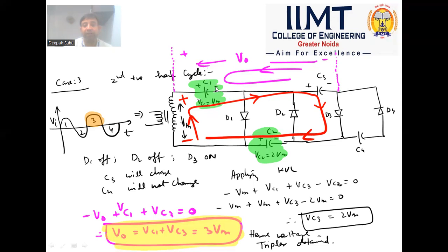So as to obtain thrice the supply, the voltages across C1 and C3 are combined to give the output as shown here, thrice the maximum input. As we see, as cycles keep moving on, each capacitor gets readily charged as per diode behavior, and their time constants are selected so that the charging time is very fast and the discharging time is kept very large. So there is very little depreciation in value and a stable constant output is obtained.